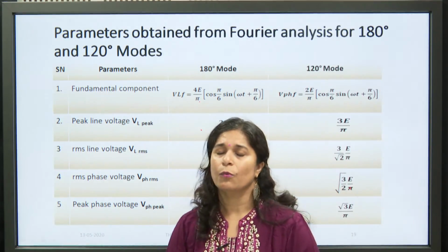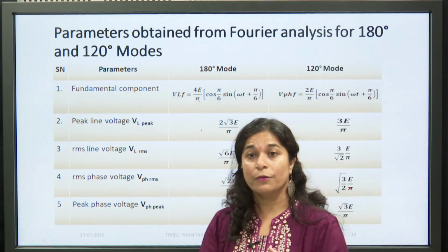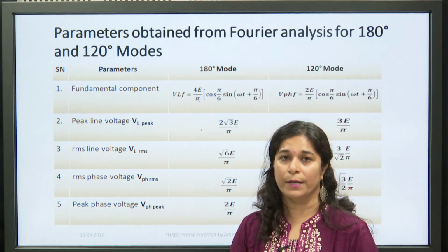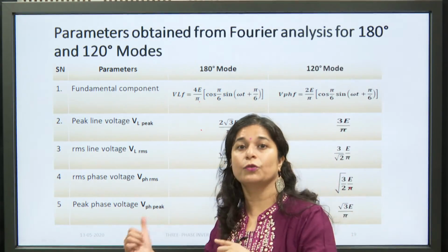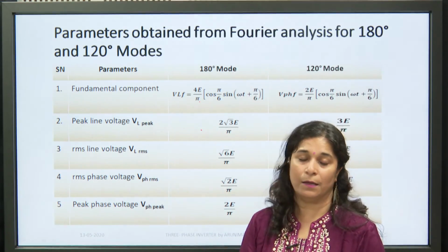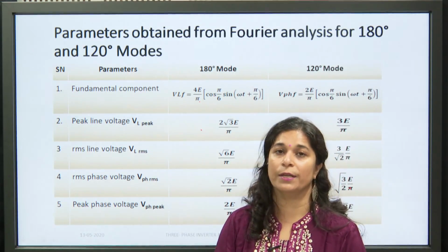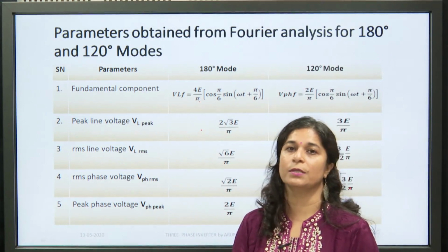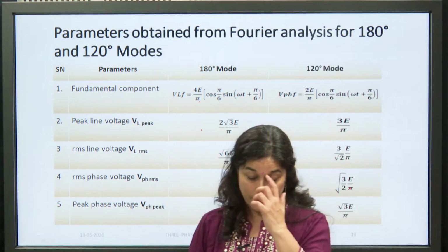So, obviously, you have to have control over the output voltage of the inverter, which is possible not through these two modes, but by applying certain modulation techniques, which we call PWM, or pulse width modulation technique.